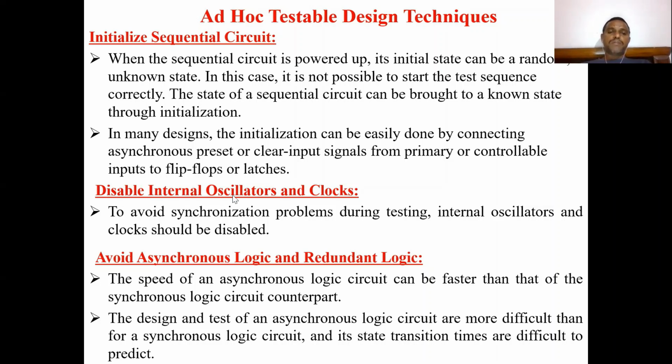To avoid synchronization problems during testing, internal oscillators and clocks should be disabled. If you apply a clock signal at the starting point, but the internally generated clock signal does not match or synchronize with it, then when you apply the test vectors, we cannot verify the design correctly.